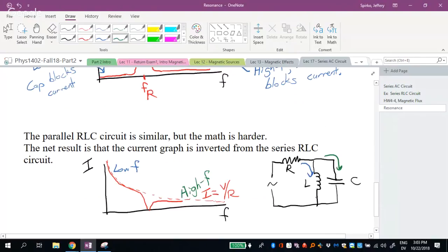And at that middle frequency, instead of either one being able to allow the current to flow, they kind of gang up on each other and block the current completely. So even though you might think, shouldn't current be able to get through the capacitor at a moderate frequency? Because the capacitor has a moderate impedance at moderate frequencies.